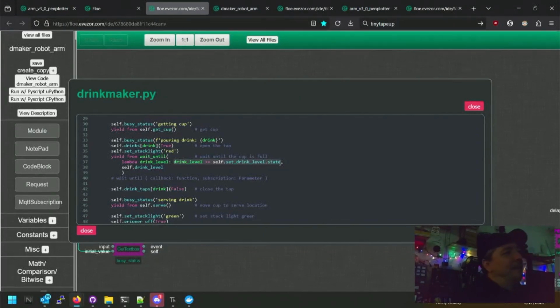Yeah, I mean, G-code has a wait function, but there's always an until because things always go wrong. What are you waiting for in G-code? Or what kind of things return? Like a spindle on or something like that? Yeah, there's a lot of things you could wait for. Like an operator to tighten a clamp and push a button. Well, that's M1. That's a little different, but I guess that is sort of a wait.